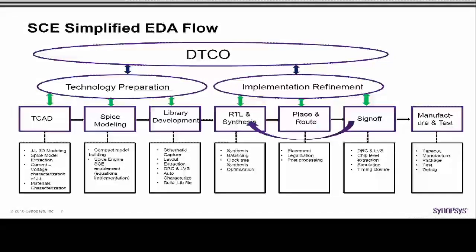What it's all about, I've put it really categorically. I've created this to put DTCO, which I mentioned a few minutes ago, Design Technology Co-Optimization, at the very top. What it stands for is the following. We are creating add-ons for every single tool in the CMOS flow, starting with TCAD, SPICE modeling, library development, RTL synthesis, etc. I will not enumerate them. And within each category, I enumerated a lot of tasks which we are doing. And again, it rhymes with CMOS, but it's a little different.